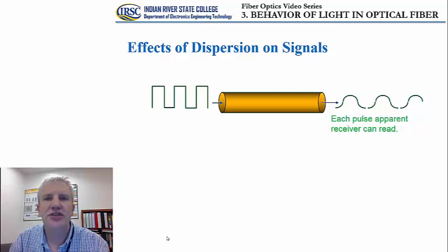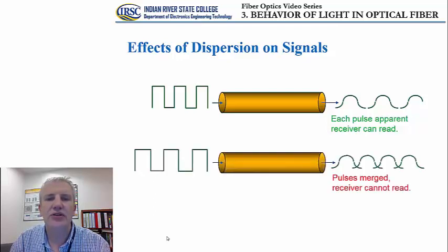So a certain change of shape of the pulses is happening as they are being transmitted along the optical fibers, but what we receive on the other side are three very distinct rounded shapes of the three pulses that the receiver can read without any kind of loss of information. If the dispersion is increased, that's going to have an effect on the shape of the pulses and also on their duration.